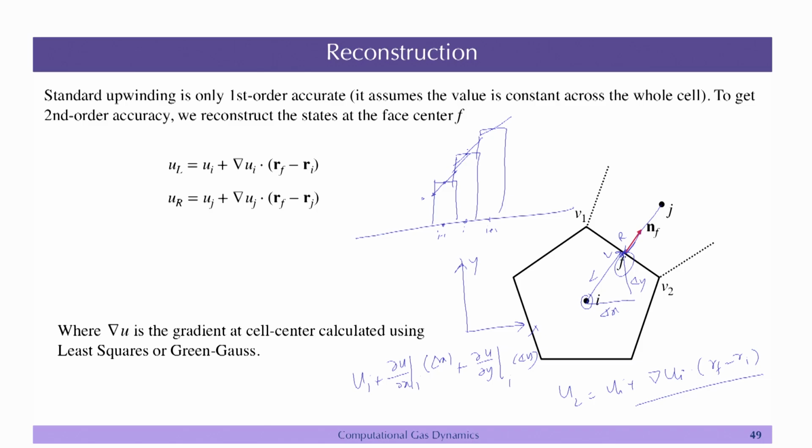If you are using minmod, then you have to select the slope which is minimum, and similarly we had slope definitions from other limiters also. Or if you are using, let us say, Beam-Warming or Lax-Wendroff or Fromm scheme, you have a certain definition of upwind or downwind or central way of getting the slope. So, how do we get the slope in the unstructured grid?